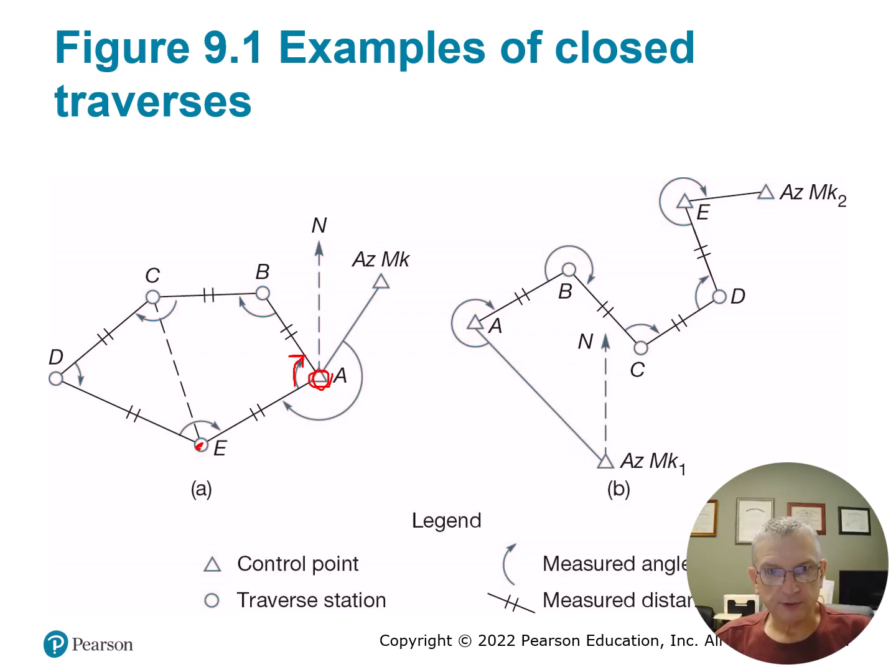Now through the course of this, you may make an angular observation onto a station somewhere for an azimuth mark. So for example, if this was geodetic surveying, there may be a published azimuth between A and the azimuth mark. Or that may be a long sight, where more commonly it might be a pair of GPS observed points so that a state plane bearing can be calculated from A to the azimuth mark.